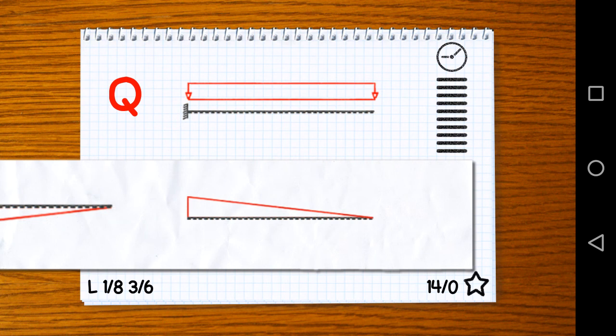Now the shear force is very good. So we use our trick again. We start reading the beam from the right side, not from the left. On the left side, we have a clamped support with 3 reaction forces. On the right side, we have a free end. So we look at the beam from the free end towards the clamped support.